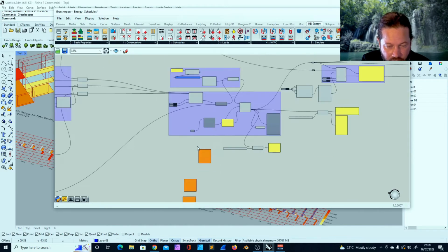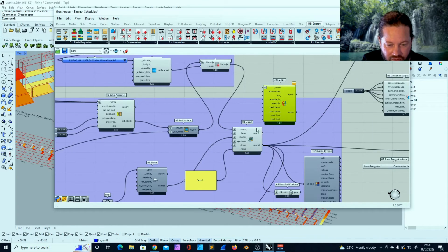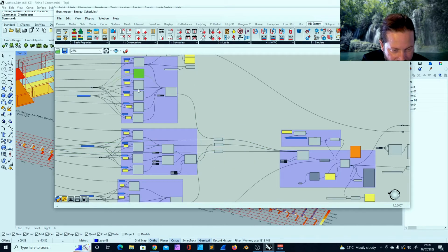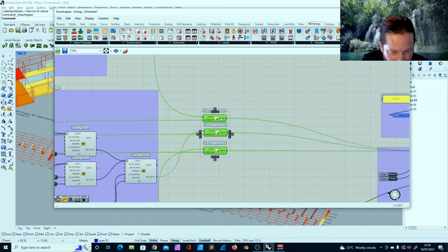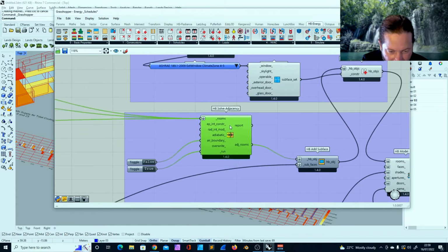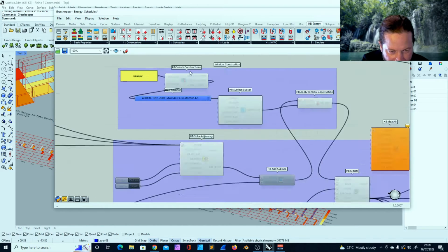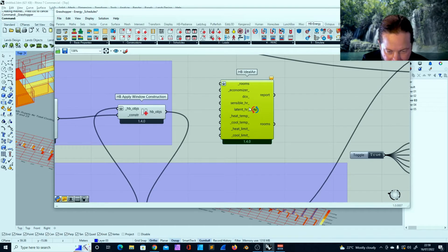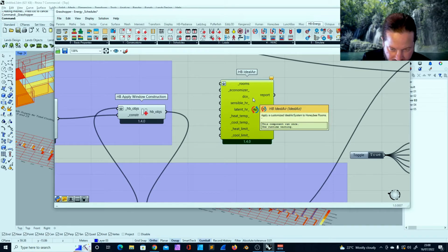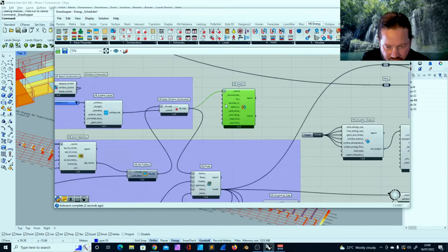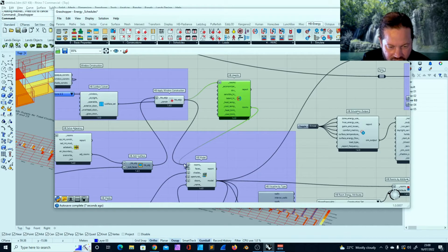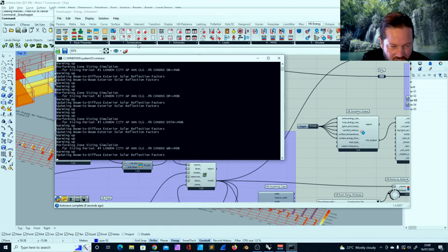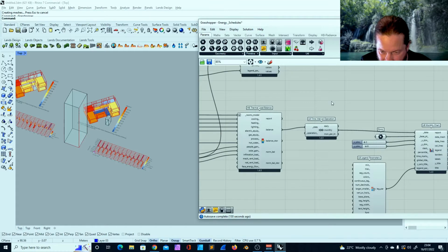But on how you apply it, it's very simple. So we could apply it now to everything, to all our rooms. And as you know, we have our rooms, our different areas here. These are all different rooms of the building. We combine these and then apply stuff to it, and then solve the adjacency of these combined room blocks. And here we applied the windows, and now, in addition to that, we could apply this Honeybee ideal air system. I'll just plug this in here. It turns green, which means there's no problem. And now if I put this in here, it will rerun the whole calculation. I did this too early because I wanted to see if there's a change. And nothing went red. It seems it worked.